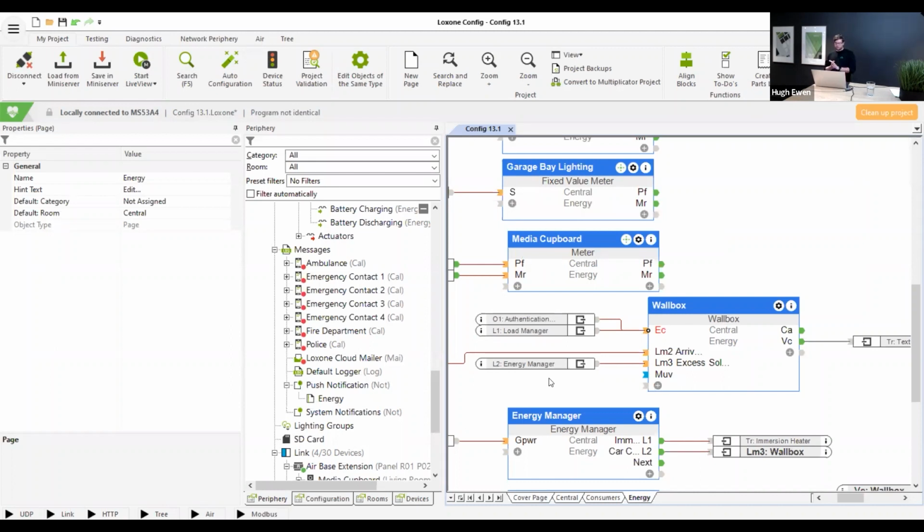So essentially, Loxone could fully replace an EV charge point, provided you have the relevant safety features, etc. DC, RCD, pen fault detection. Loxone can then load shed, delay charge start times, but you have a much more capable unit. Yeah, absolutely. I would say with the new Wallbox function block, we have just taken every USP that every car charging company has, and we put it into a single block. So if company X only do this, and that's their USP, and company Y have this, and that's their USP, the Wallbox function block probably does them all.